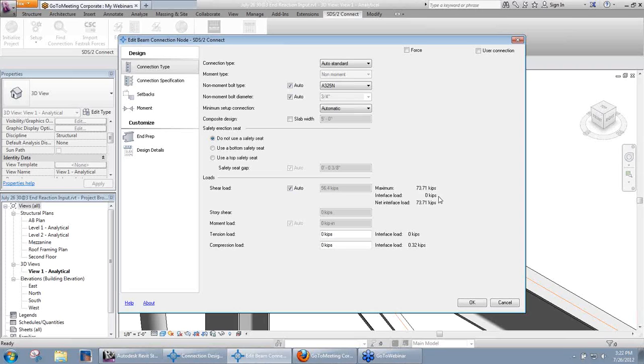So that is actually being accounted for now in the gusset to column connection rather than the beam to column connection. Kind of have to watch out for those interface forces a lot. The reason being is a lot of times with the extra force added, you do tend to get some failed connections for your beams. So just something to watch out for there.